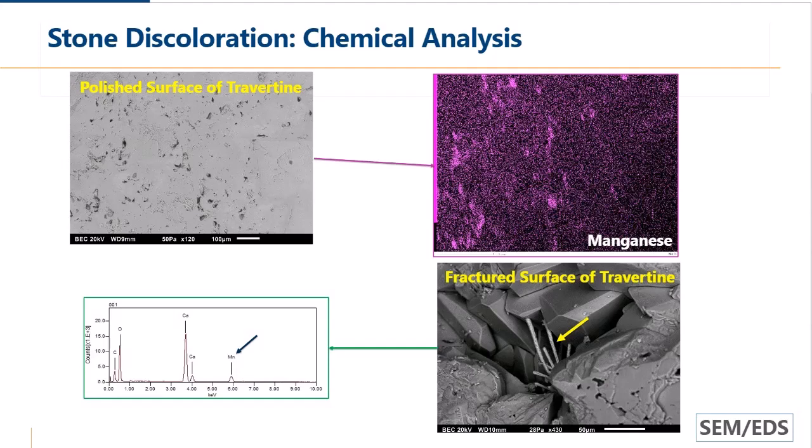manganese, abbreviated Mn. Other methods of evaluation that were not used in this case study, but may be helpful in stone discoloration analysis include X-ray fluorescence, which allows for more quantitative concentration measurements of the elements on the surface being analyzed. X-ray diffraction, like brought up previously, which identifies the crystalline components in the sample, or methods used to detect organic materials, such as GCMS and FTIR.